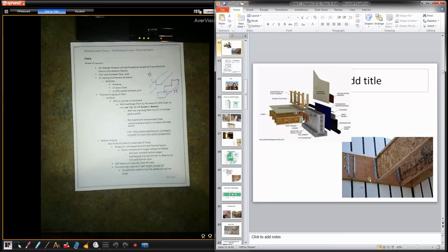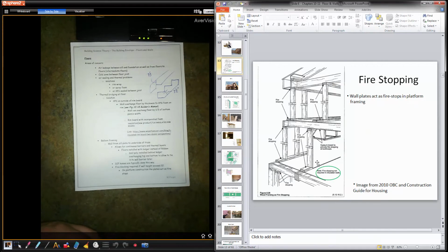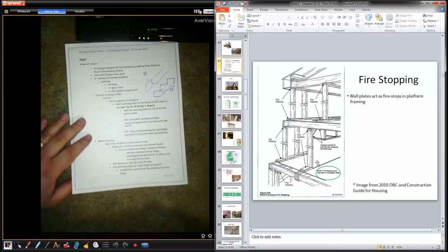And then again, not necessarily to insulate this area, but some people might add more insulation there, make sure it's nice and warm. But there's probably about 3 inches of foam here and 3 inches of foam here, or maybe it's 2 inches of foam. That'd be 4, yeah, that's more. So more than likely from outside to outside is 10. There's 2 inches here, 2 inches there, and there's 6 inches of concrete, lots of rebar in there. So you can see they're going with this place. It's going with a double wall, so really trying to make sure that it's nice and warm.